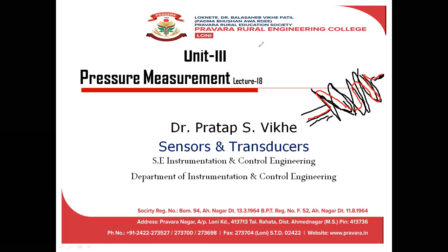Why are we calling this an elastic sensor? Because this is going to be elongated when we apply the input pressure to this helical type of Bourdon tube. So this will try to move in the forward direction, and the pointer is connected to the upper tip, the existing point across the pointer. Here is the scale, and it is trying to highlight the structure.